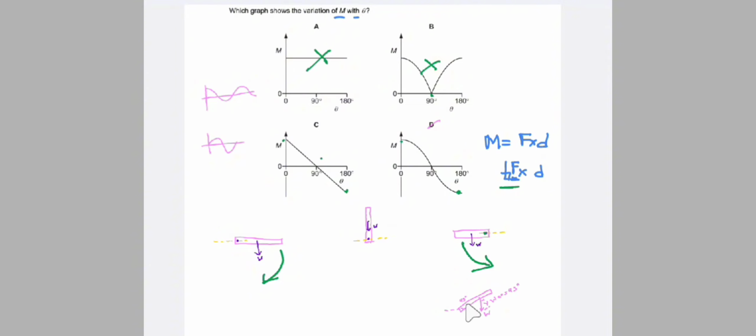First of all, if we consider the angle of 45 degree, that means the rod is at an angle of 45 degree, then the weight is acting vertically downward. If we break the weight into its components, the vertical component is W cos 45 and the horizontal component is W sin 45. And what is the moment? Moment of force is the product of force and the perpendicular distance from pivot to the line of action of force. So the force has to be perpendicular. Therefore, we consider the perpendicular force with respect to the pivot, which is W cos 45. So this is the moment that comes.